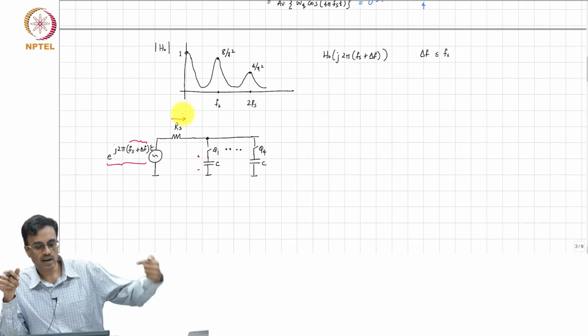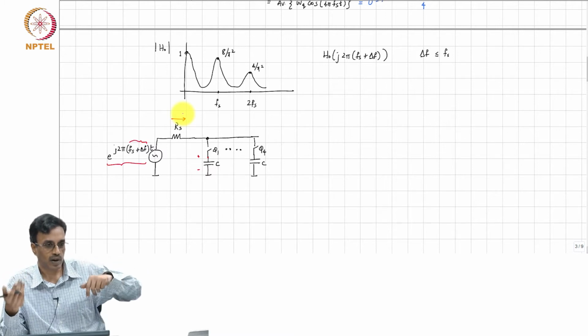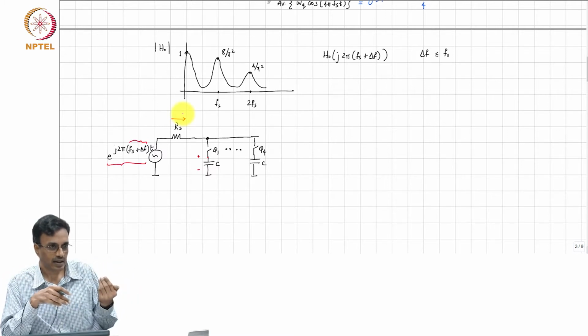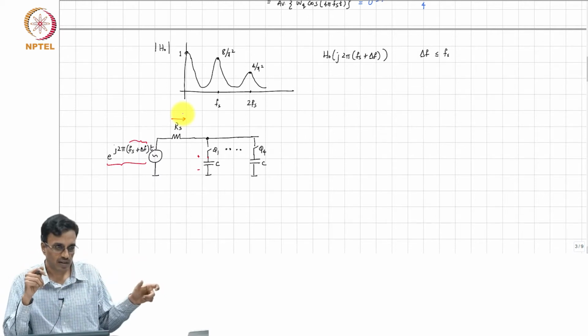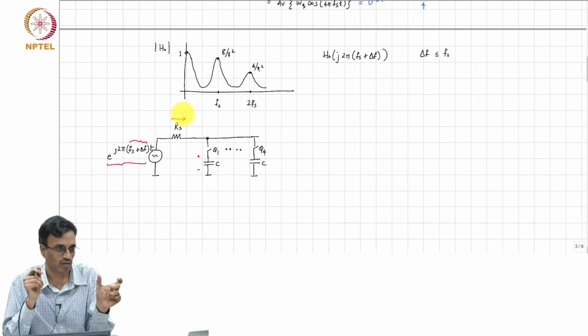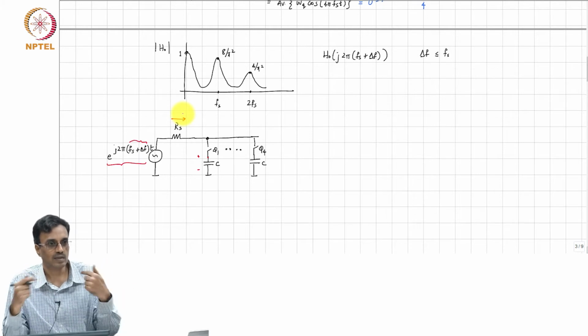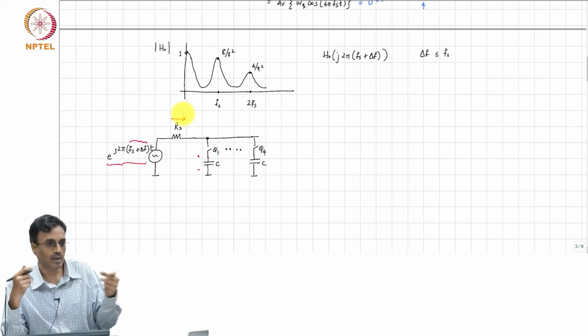So, what is going into the capacitor is the low frequency component, which happens to be DC, correct, okay. And at the same time, the capacitor is trying to discharge through the resistor, which is connected only for a fraction of the period. So, when the two effects basically equal each other, you will have an equilibrium voltage, right.